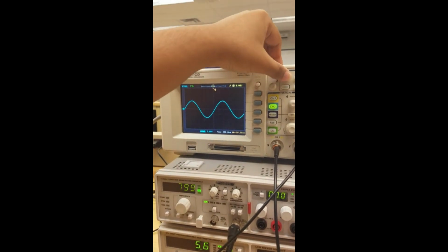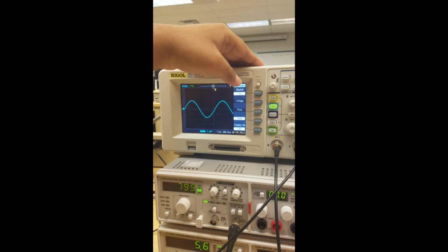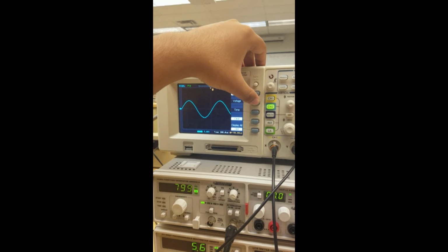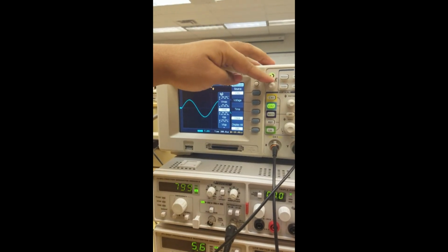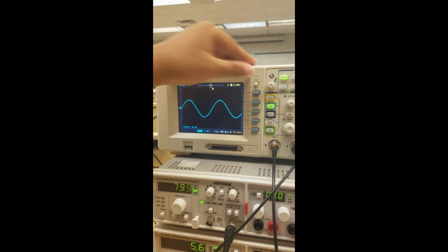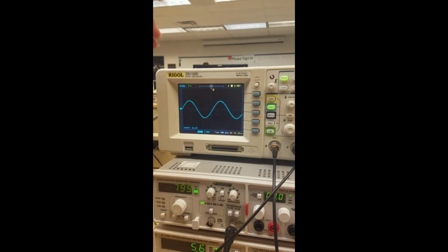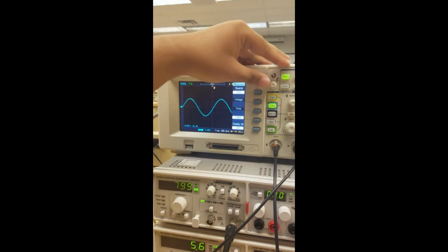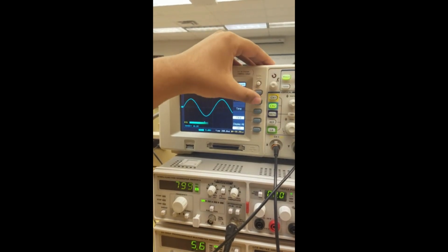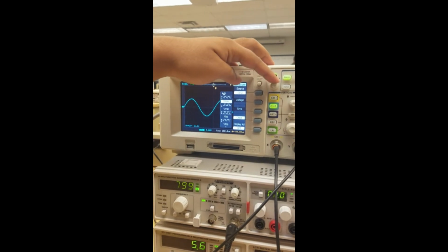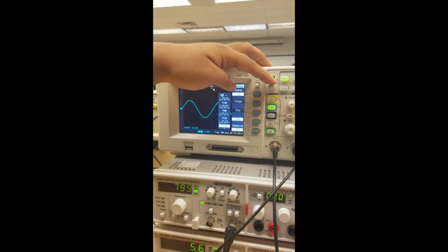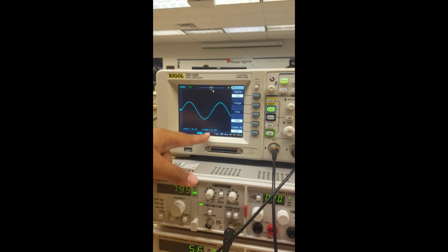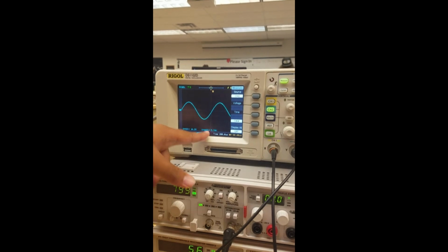You will go to measure, and to measure peak to peak for channel 2, you want to go using the new way. You want to go to voltage, scroll down to peak to peak. You get 16.2 volts for the peak to peak, and then you want to go to measure RMS for channel 2, and go to the same place and scroll down to VRMS. You'll get 5.75 volts RMS.